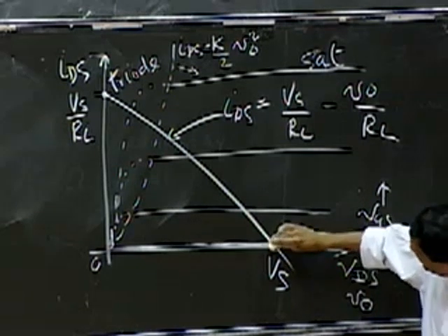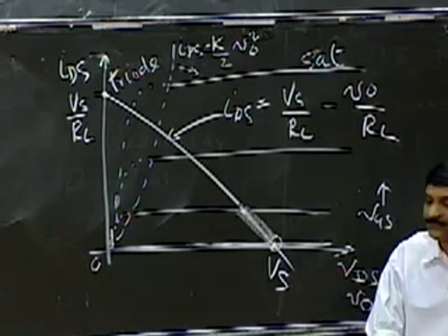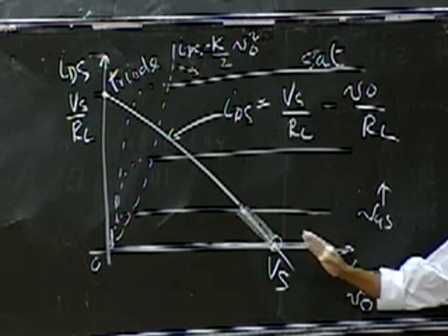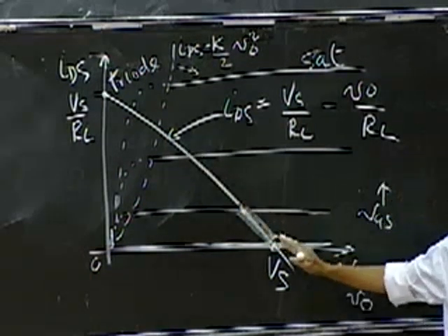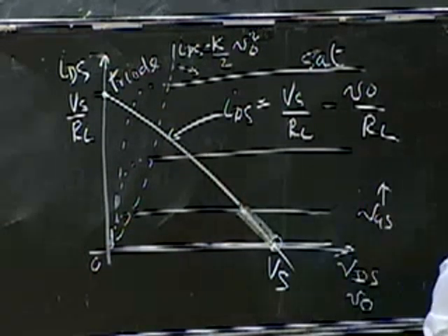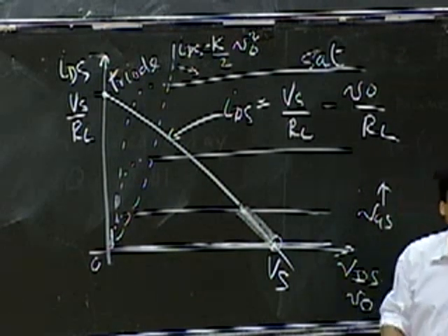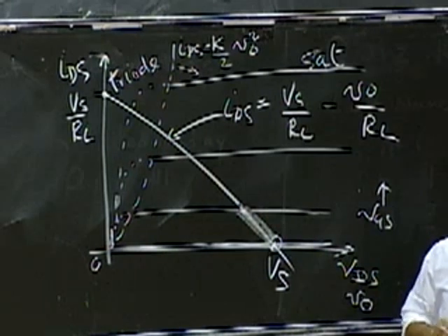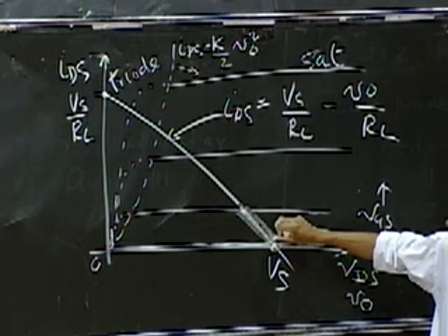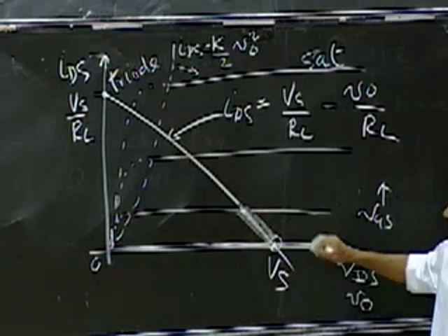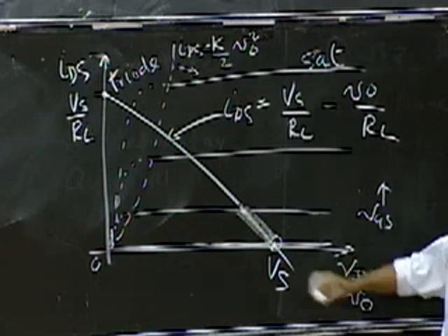So it's here and somewhere along that load line. Remember, the load line is a constraint that must be met by the output V naught. Okay, it's the constraint imposed by KVL on the output. Okay, so the output is constrained to operate in this regime for various values of VGS.